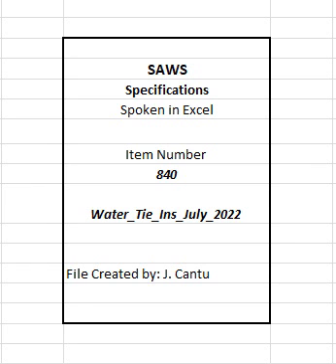2. Connections between new and existing mains which are made with cut-in tees and tapping sleeves and valves will be processed as separate pay items in accordance with SAWS specification item number 831 and item number 832, respectively. 3. Temporary water mains, 4 inches or greater, will be processed as a separate pay item. 4. Cut-in valves will be processed as a separate pay item.